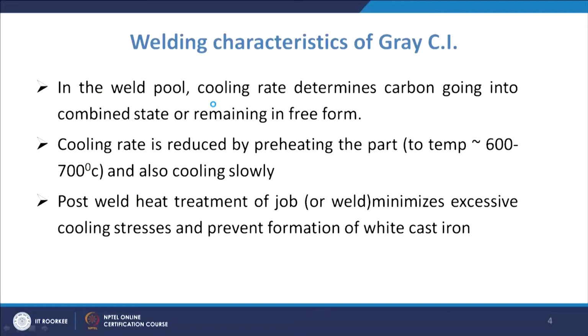So, you will have to reduce the cooling rate, and that is normally done by preheating the part to a temperature of maybe about 600 to 700 degrees C, and then cooling slowly.